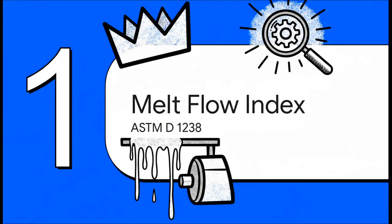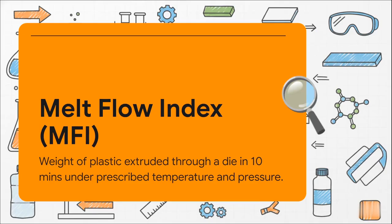Starting with Section 1, the Melt Flow Index, or MFI. If you study literally nothing else today, lock your focus in right now. Here is your exact ASTM D1238 exam definition. Write this down. Melt flow index is the weight in grams of molten plastic extruded through a specified die in 10 minutes under prescribed conditions of temperature and load.